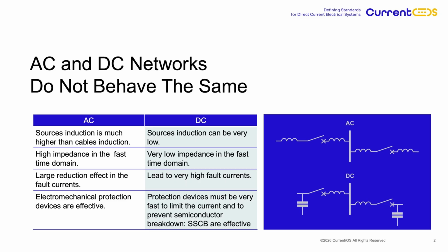By the time they attempt to open, much of the capacitor energy has transferred into the inductance of the cables, and the breakers must then dissipate the stored energy in the cables. For a multi-source system like a building, this presents a major challenge. Calculating fault energy becomes highly complex, requiring detailed knowledge of every capacitor in the system.